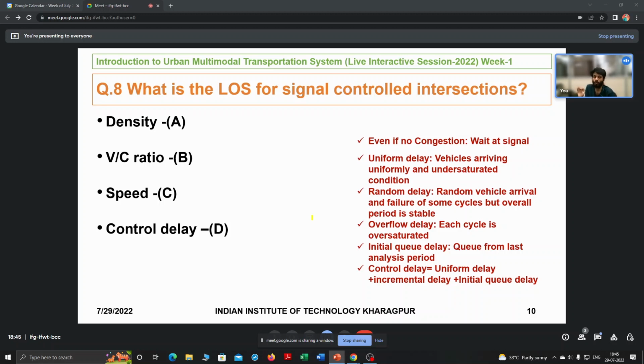So then the uniform rate of arrival, it is not that every 5 minutes the rate is changing, somewhere it is 1200, then it is 14, then it is 2. It is not that kind of graph, it is like a simple graph that 1200 vehicles are coming in an hour, right? So whatever the delay is, that is called the uniform delay, because the rate is uniform.